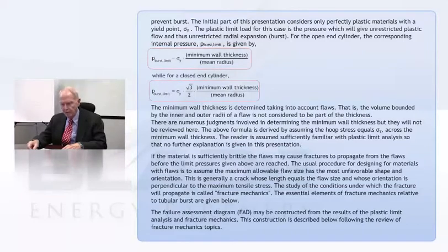The place where fracture mechanics comes into this is that it's known, and in fact they're measured, that these pipes have flaws in them. They have some ways of trying to measure flaws, usually acoustically. I don't know that at this time they're able to really do a good job, but they do their best. And for certain kinds of wells, every pipe that goes in the well is subjected to measuring the flaws in the pipe. So the thing would be then, what do you do if you know what the flaw is? If you're making measurements, you ought to be able to establish some limits on how big the flaws will be.